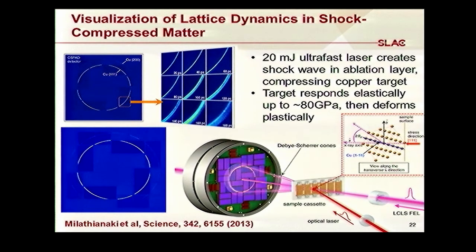It's a fairly high power laser focused onto the specimen. Here is a piece of copper, and what you're looking at is the diffraction from the copper lattice. And every shot, you basically destroy the sample. You have to move to the next piece. Now, if you do that and you accumulate at different times, you will see the diffraction ring get developed. You see the breakup. So from that, you can then analyze the strain rate of the material.